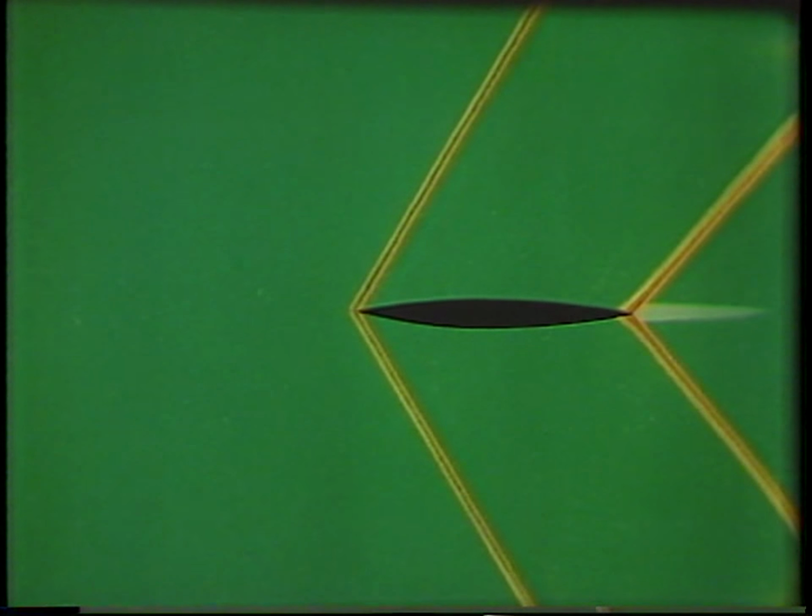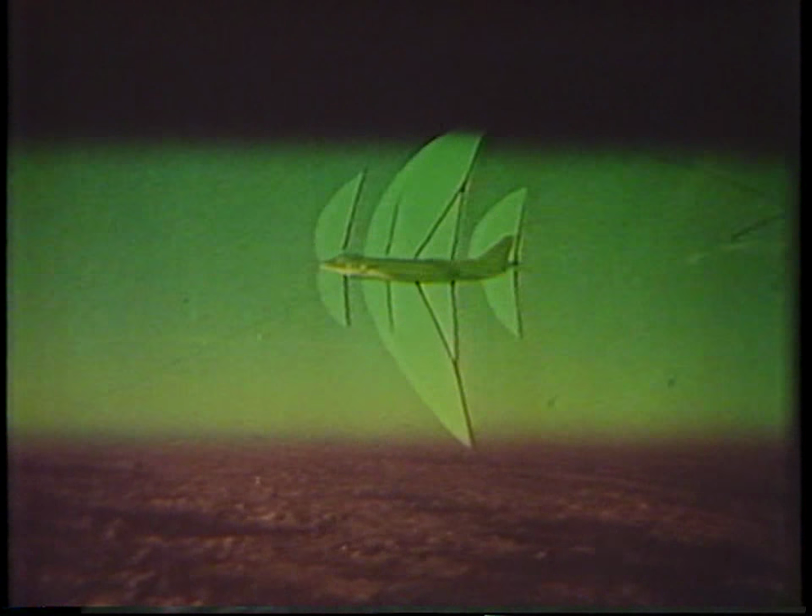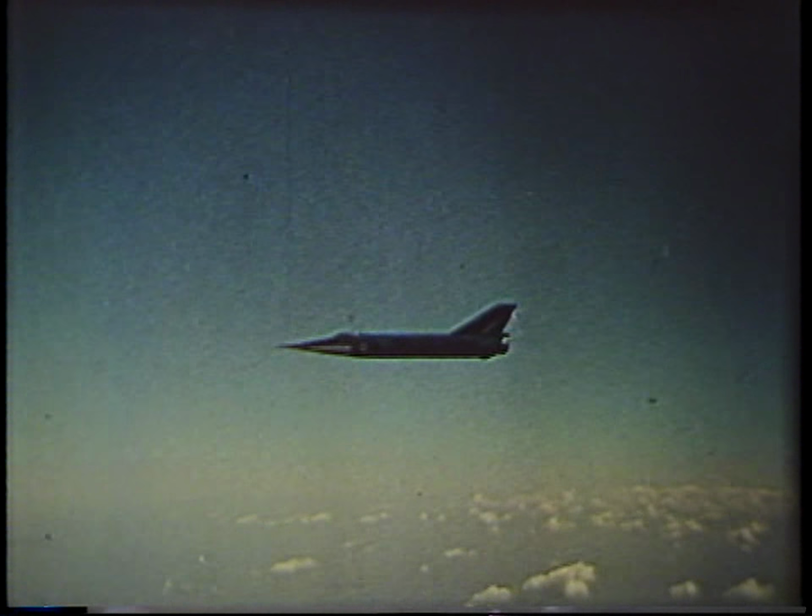So when considering airflow, it's convenient to divide flying speeds into three ranges. The subsonic speed range, covering all speeds at which the flow everywhere around the aircraft is subsonic. The transonic range, covering all speeds at which the airflow is mixed, part subsonic, part supersonic. That is, from M-crit to about Mach 1.3. And the supersonic range, covering speeds at which the main flow everywhere is supersonic.